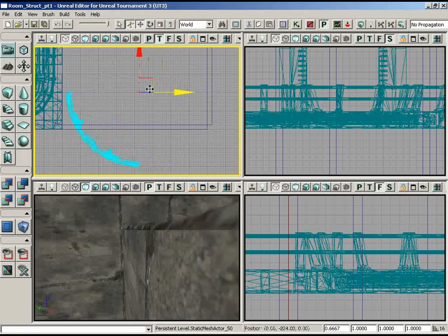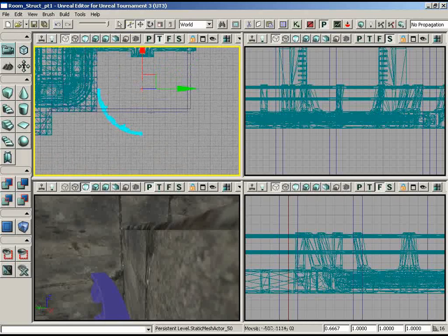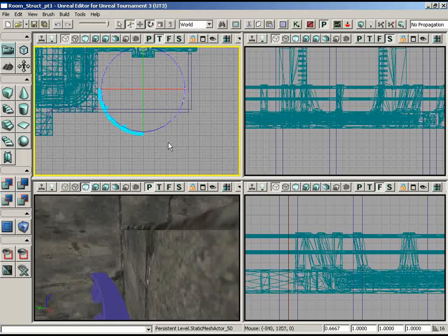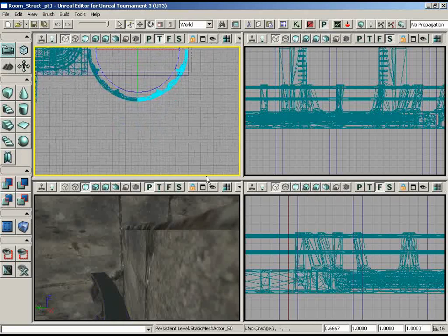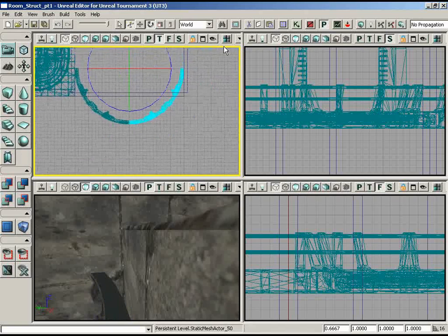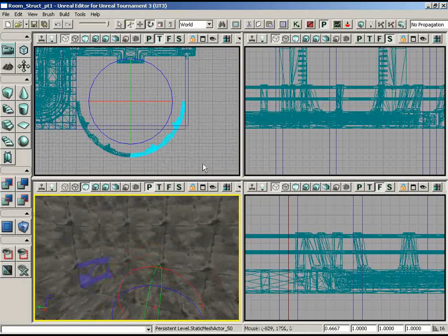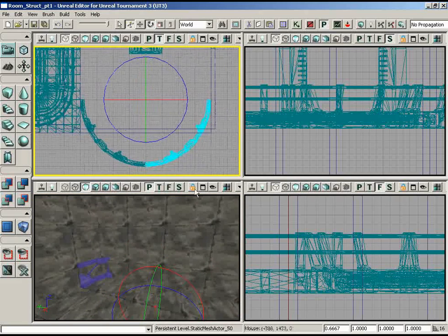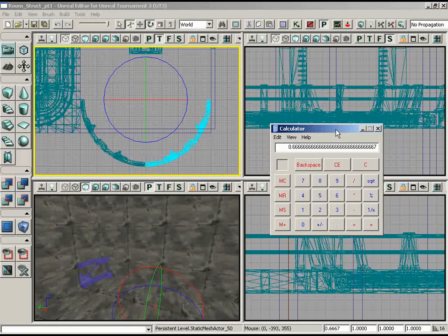Push that on back over. Oh, I see what's happening. I actually need to divide that by 2. If I duplicate now, let me switch to rotation for just a minute. Hold Alt and duplicate, and the position of the pivot on that mesh is convenient because you can duplicate and get a semicircle or even full circle result. Now that is exactly twice as large as I want it to be. I want to fit 2 of these in here instead of just 1. So we actually need half of this. So we could divide this down by 2 and we get 0.33.